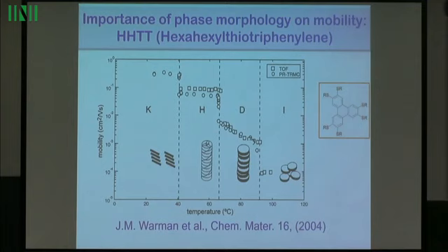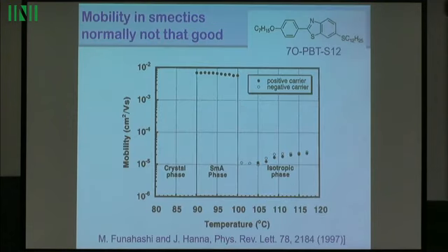And if you have discontinuities, domains not with exactly the same orientation, so-called grain boundaries, then your charge mobility is lost at that point and the material degrades completely. So you start to see that it would be nice to have design principles or techniques to try to optimize, or anyway to predict, this type of behavior and perhaps improve it.